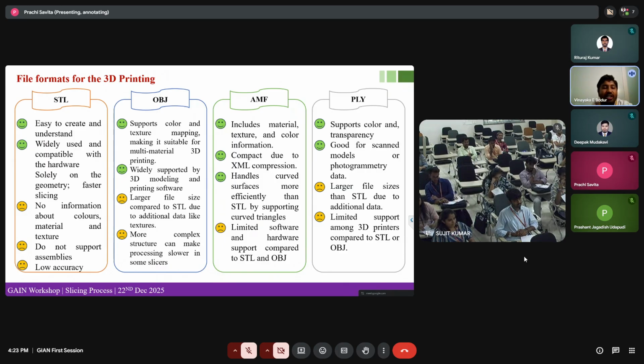The multi-file structure introduces significant logistical challenges. If the MTL file or the texture images are missing or incorrectly referred to, the visual data is lost, leaving only raw geometry. When I say MTL, it is referenced by the OBJ file itself, where it gives material properties and also the texture images, in which texture we need the printing to happen. Additionally, the inclusion of high resolution texture maps significantly increases the file size and the computational load required for slicing.